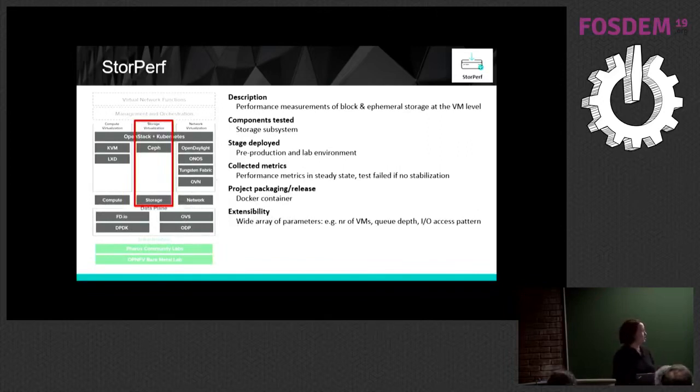And in terms of extensibility, you can modify the parameters, such as what you define as steady state. You can define a set of hysteresis or how long it's supposed to run for. And if you end up running it and you don't reach a steady state, it lets you know that as well.